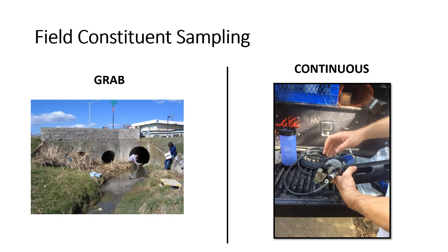Alternatively, they have these newish devices called water quality sondes. That's what one of them looks like. This is a YSI EXO. YSI has some really fancy technologies for doing these things. This device, this blue-looking thing, you mount in the bottom of the stream, and it's got different sensors mounted to it. Depending on what you want, you can purchase different sensors and interchange them.